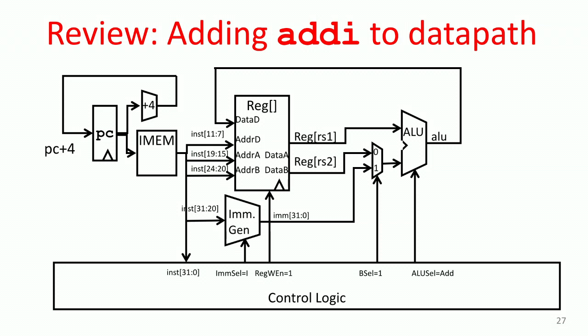So previously, for the add immediate instruction, we took the result from the ALU, and we just sent it back into the register file. Now, instead of putting that value in, we're going to treat that as a memory address. So we want to take this value here and send it into the data memory, not shown yet, or in practice the data cache,